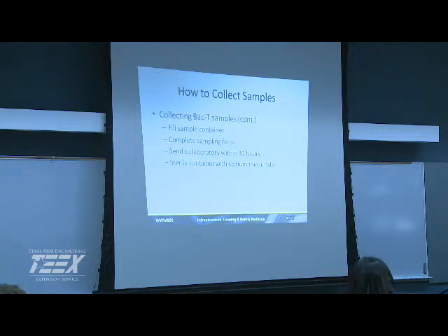needs to be sterile with your sodium thiosulfate. Some people add it. It's easy enough to buy it with the tablets. And do we know how much those tablets will neutralize of our chlorine residual? Any ideas? How many milligrams per liter? About 15. Okay, so you can have a pretty hot sample and still be able to dechlorinate it properly. About 15 milligrams per liter, which is pretty hot.